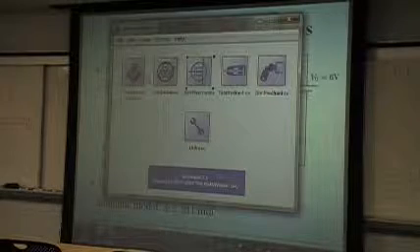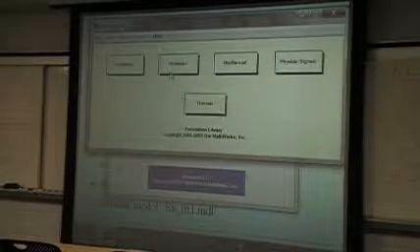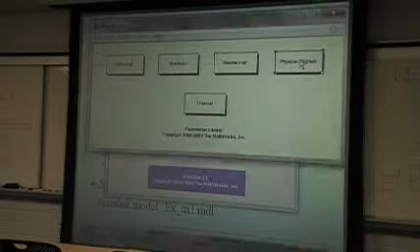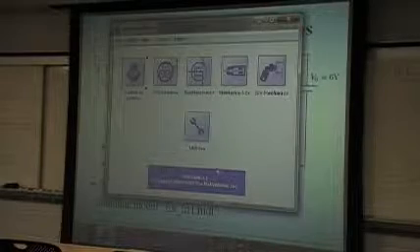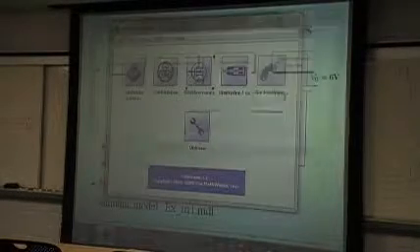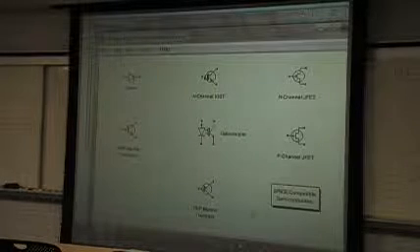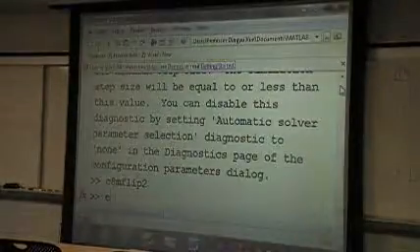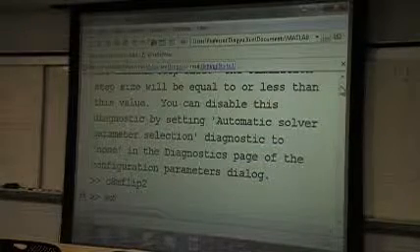Use the foundation library, and inside it, here it should be in electronics. And there are some semiconductor devices. And we can use this kind of blocks to model the original circuit. And the model is given in 3.1.